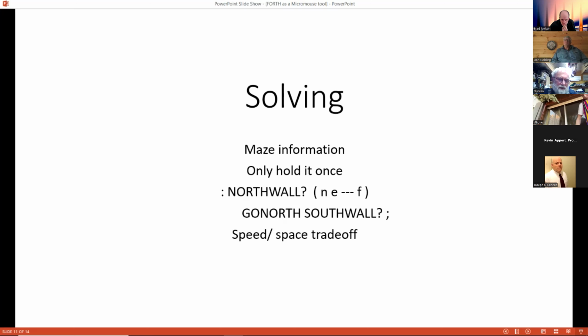So I only hold west and south walls, but I have to use a 17 by 17 array to allow for extra cells around the edge that hold these south and west walls. On previous mice, I've packed flags into bytes and unpacked them for use. This enables a single byte array for all the mouse data. It works, it's fine. It's what I'll be showing you in a minute.